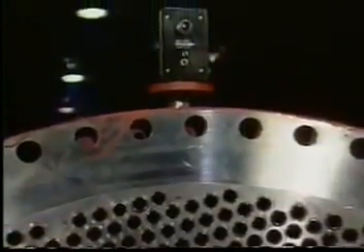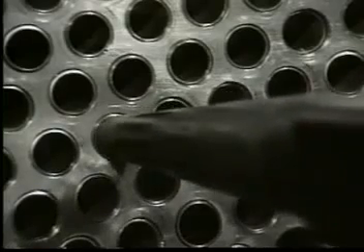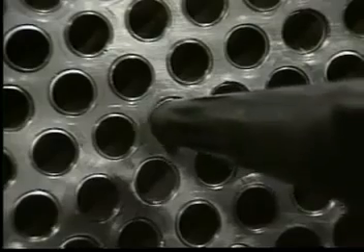UE Systems WTG-2SP warble pipe tone generators are used. Use as many tone generators as may be necessary in order to achieve as uniform an ultrasound field as possible around the tube bundle. As an example, place one in the inlet port and one in the outlet port. Proceed as with the other leak detection methods, scanning for the sonic penetration of the warbling tone.